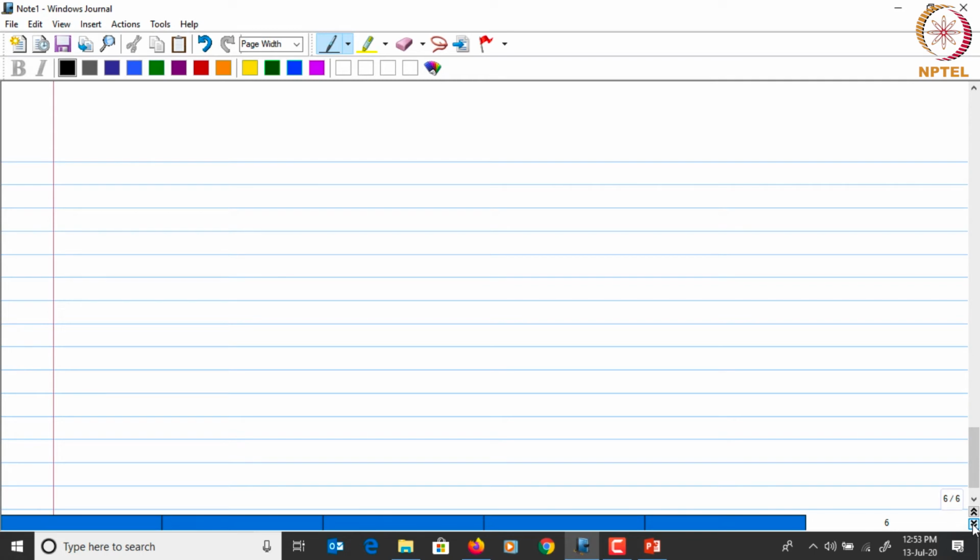And the other aspect which is again beneficial for the sintering process is the creation of vacancies at the interfaces between the metal powders. Okay, you have two different materials and there is an interface, so that leads to creation of vacancies, which is again good for the diffusional process to occur, and this also retards the grain growth.